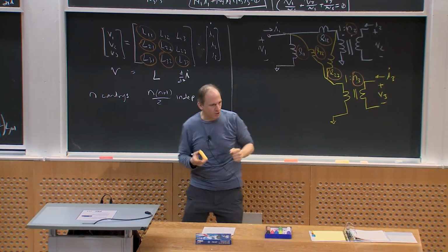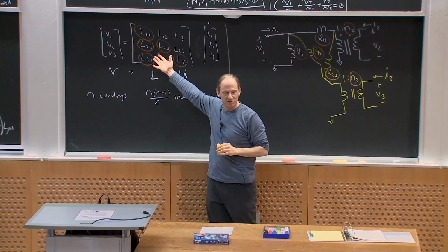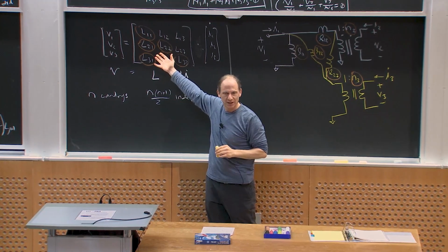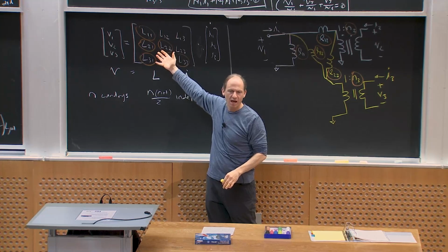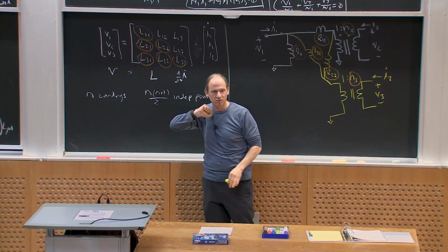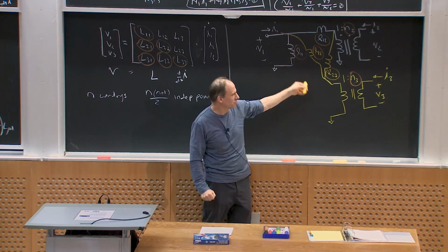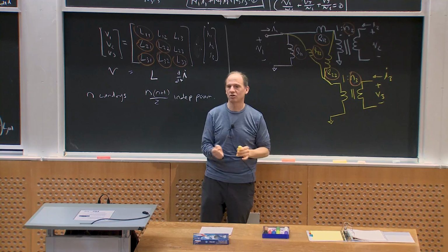It also turns out that all these parameters can be directly related back to the inductance matrix values. Okay? And I put the equations in there, and exactly how you do it. But the nice thing is, if I have an inductance matrix description of the thing I wanted, I can create a circuit model that has that. This is a non-physical circuit model, but it matches the terminal relationships.